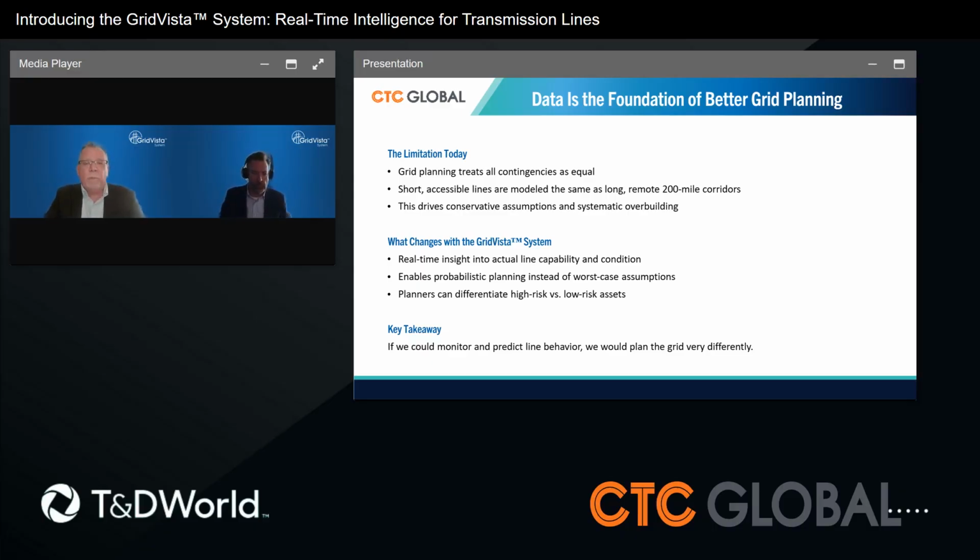We need to help prioritize grid enhancing technologies for transfer increases and needs that may be less than 20%, and high performance conductors like ACCC in general and GridVista in particular for needs where we identify greater than 50% overloads when right sizing opportunities are observed in planning studies. This is consistent with the Brattle study recommendations that I supported less than a year ago for better implementation of transmission planning per Order 1920.